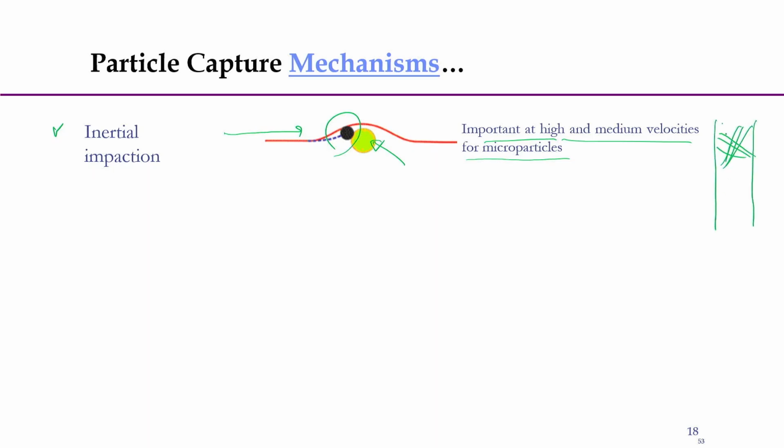So this is a filter media. So, smaller particle at high speed it is moving. So, it will strike the fiber, and that impact will actually reduce its speed, and the air is flowing out, but the particle is settled within the structure due to the inertial impaction. It will lose its energy and it will get settled within the structure.